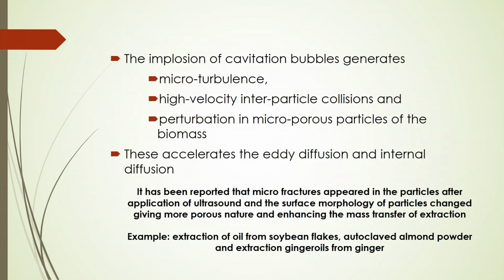Also, the implosion of cavitation bubbles generates microturbulence, high-velocity interparticle collisions, and perturbation in microporous particles of the biomass. This accelerates the eddy diffusion and internal diffusion. It is reported that micro fractures appeared in the particles after application of ultrasound, and the surface morphology of the particles changed, giving a more porous nature and enhancing the mass transfer for the extraction, like extraction of oil from soybean flakes, autoclaved almond powder, and extraction of ginger oils from ginger.